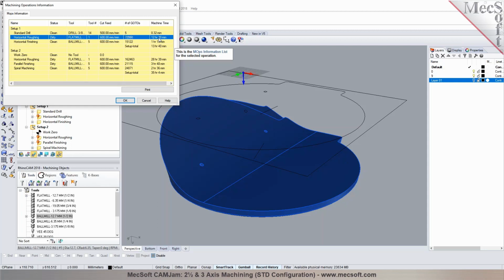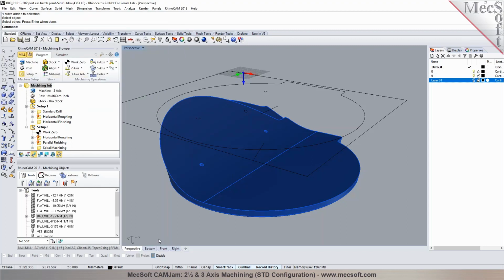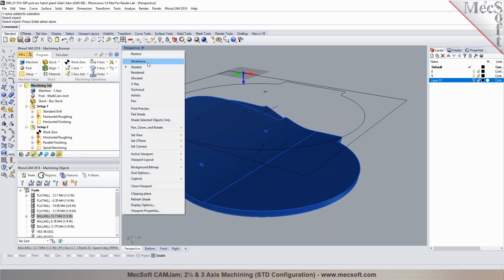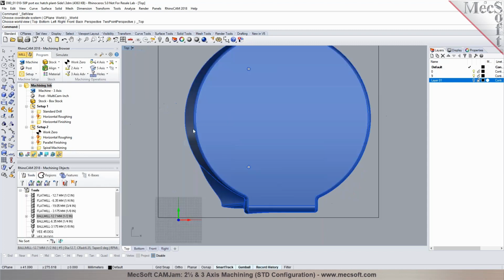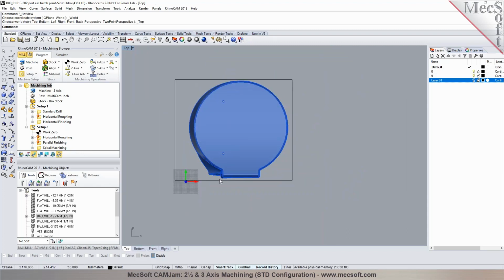So you see that the roughing is going to be the longest time in here when you're cutting it from the other side. Maybe you could do an operation to go ahead and clear out some of the excessive material and then just have it rough in some of these areas in here. So if you take a look at it from the top, you could actually just put an area just around here to rough it out. Right, I see. And not have it do the entire areas in here, so you can basically contain it, and all of this can be cleared out in a different process with a much larger cutter. Right. So you can get down a lot more because it's flat.